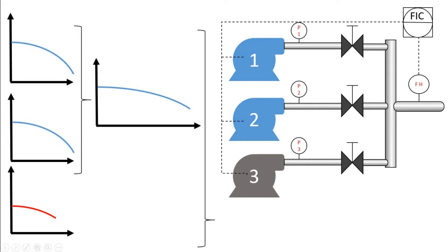But anyway, we have a header and two pumps, and the two pumps are identical and are running at the same speed. We have a bias which compensates for differences in pump efficiency if one of them is brand new and the other one is an old one. So in this system, we have no problem. We have two identical pumps, so the net result is multiplying the flow rate while keeping the same head. So we shouldn't have any problem if the two pumps are identical.